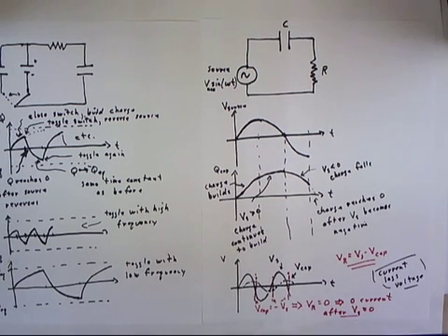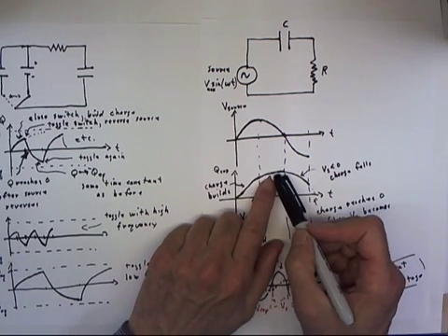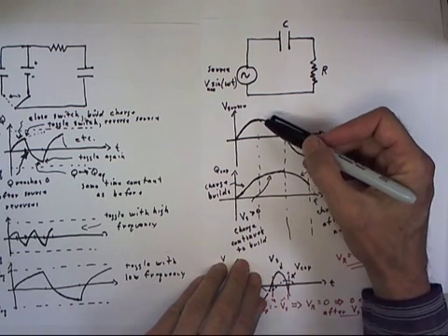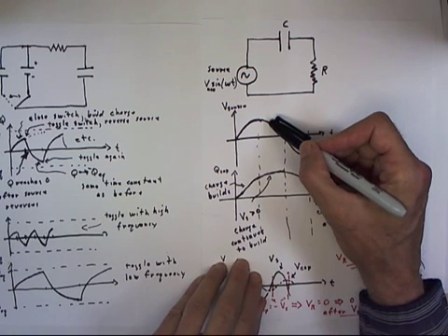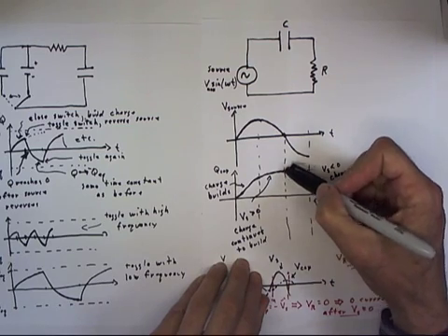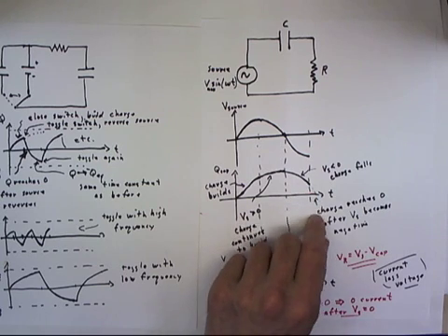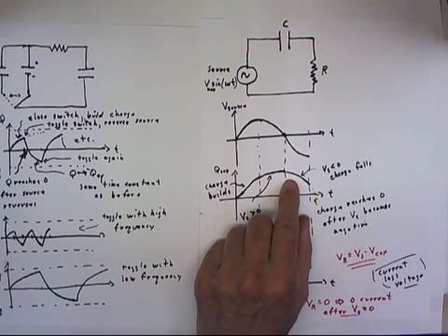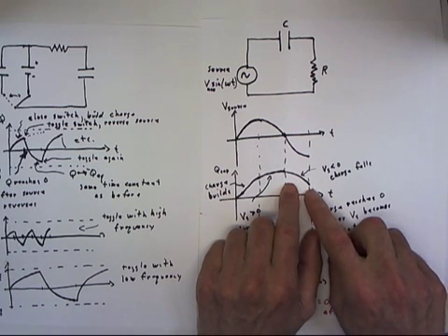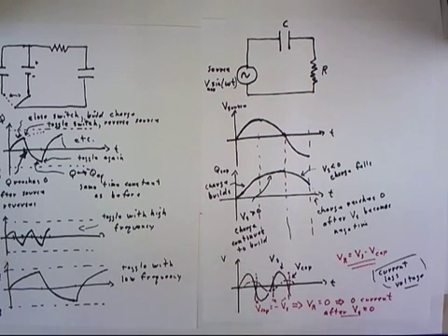The problem is that as the charge builds, the voltage in the capacitor builds. So the charge begins to fall when the voltage on the capacitor is equal to the voltage of the source. So that's going to occur before the voltage of the source falls back to zero. So pretty much this picture is invalid. I kind of knew that before, and I should have looked a little more closely at it before I started talking about this. Since we haven't gone to that point, I think there's no harm done. We'll fix that, and we'll continue on in the next clip.